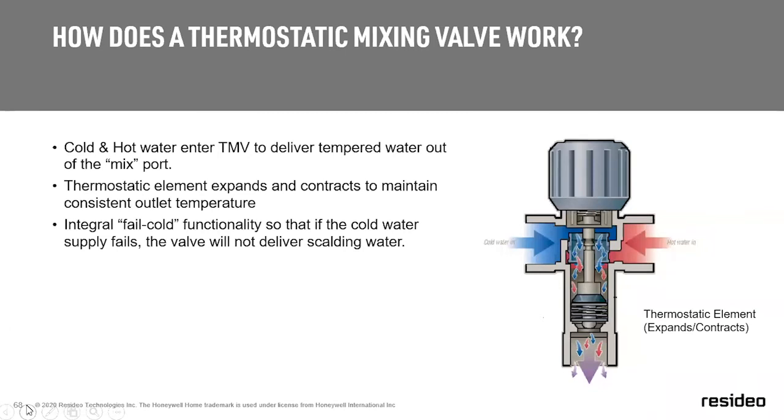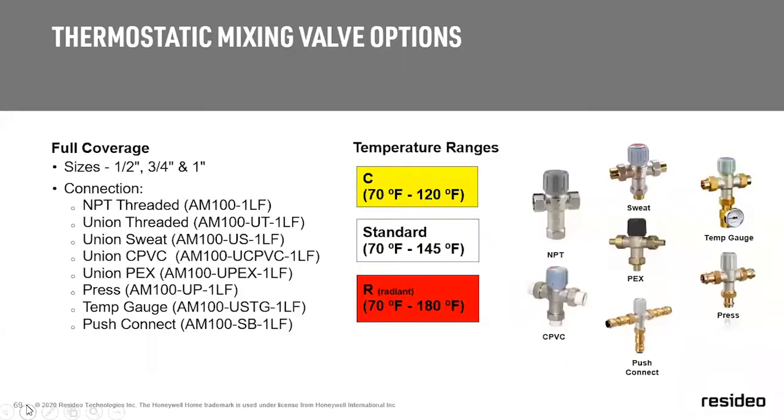Mixing valve, AM mixing valves. They've been tried and true for us. It's a common application. We also want to scald proof the whole house on domestic hot water. There's still 40,000 scaldings a year that take place across the USA because the whole house does not have a temperature valve, thermostatic mixing valve on it.